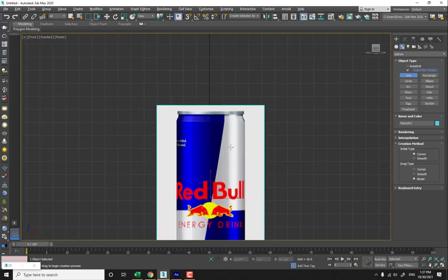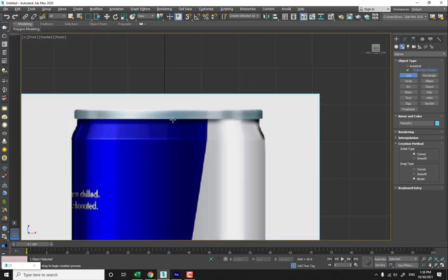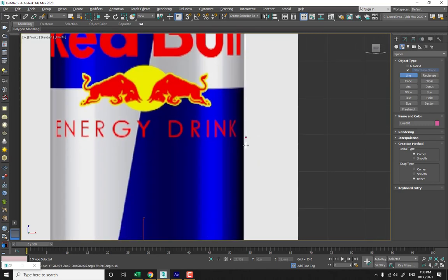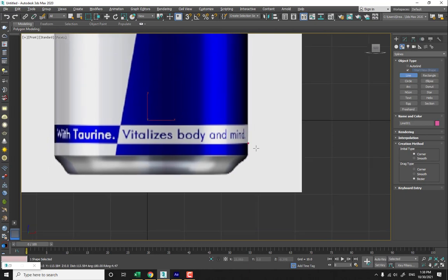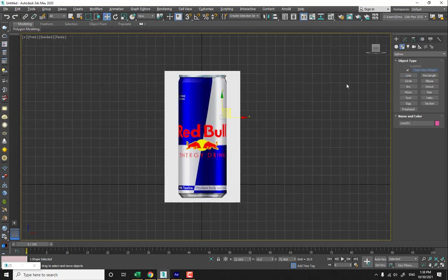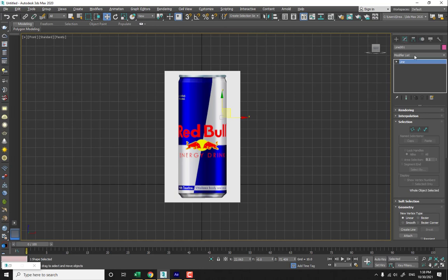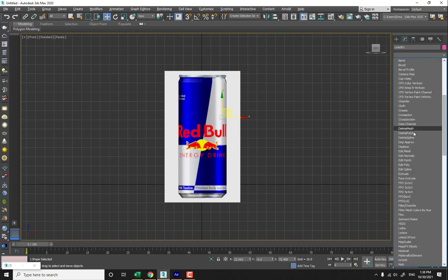There is the easy way. Select the line and click here and move to here and move to here, then here. Backspace for deleting the point and press shift, then click here. Right click for stopping the line creating, and then go to modify.